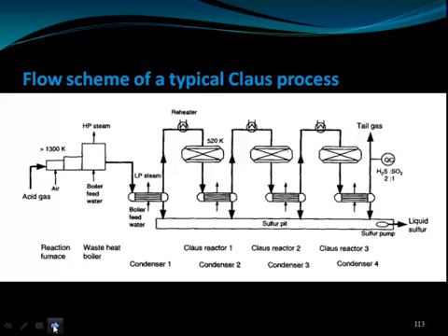Generally this is done in a waste heat recovery boiler, WHRB. Then low pressure steam is also formed by the further cooling of the acid gas stream, when it is sent to the reactor, and after various stages to the sulfur pit, where the H2S is oxidized.